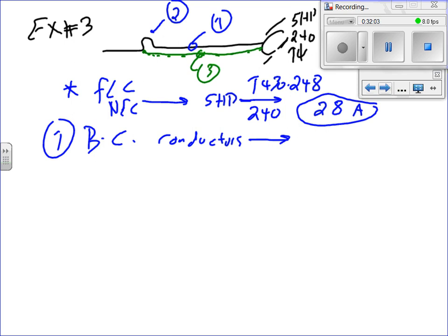Motors are continuous load. Write yourself a note, and that would be 1.25 multiplied by 28. Who did the answer? 35. When you do your calculation, if it's 35.5, go up. If it's less than 35.5, go down. Is that 35 even? 35 amp, great. And then you take the 35 amp, take this one to the table, which table?